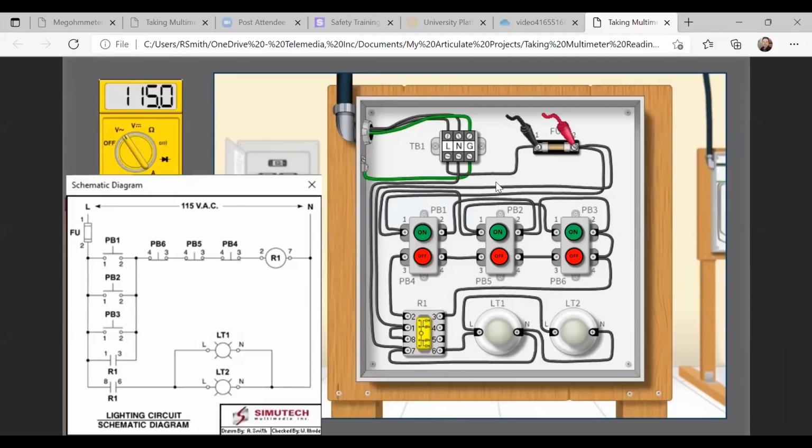You want to avoid measuring from top to bottom of a fuse in a 480 volt, let's say 3-phase system, because if that overload is happening on the high voltage, your meter can actually be the new path for current to flow. So I know someone was asking earlier,